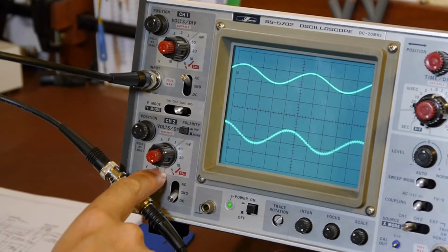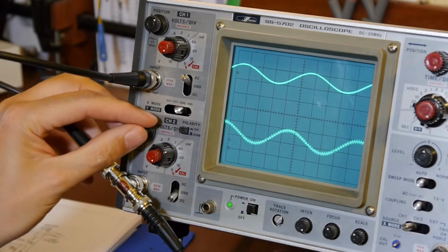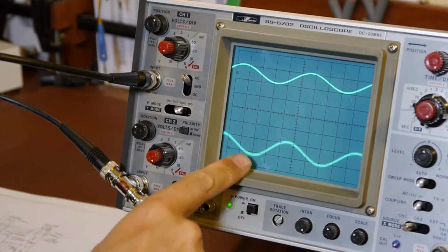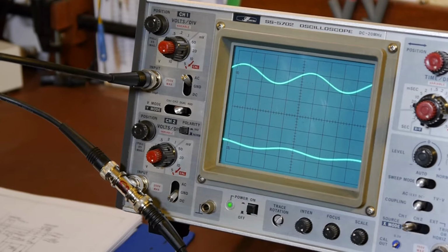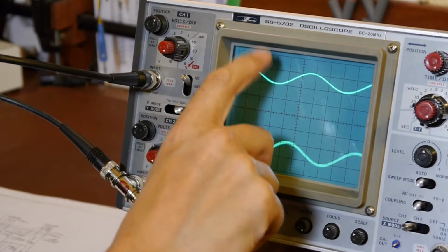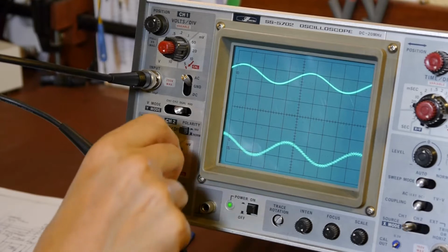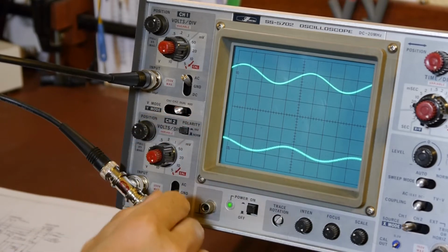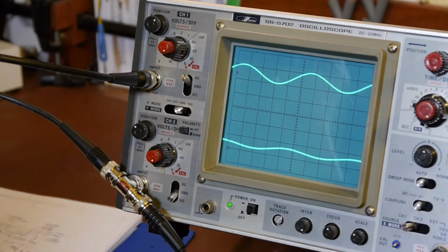But the 10 volt range and the 5 volt range are working, so that should be about a division now, and it probably is about a division if we put the noise onto it. But if we put it to the 2 volts range now, this should be twice as big, and it isn't. And if I go to the 1 volt range, it should be bigger again, which it is a little bit, but I'd expect this to be 5 divisions high now, and it's not. And now finally, if I go to the 0.5, again we'd expect it to be pretty much off scale now, and it's not. If we go to 0.2, it works normally. So there's something wrong with the 0.5, there's something wrong with the 1, and there's something wrong with the 2. But the 5 and the 10 is fine.